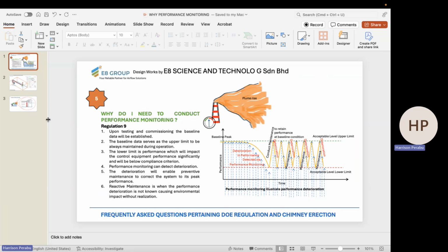Now, this notification process is actually also an engineering design permitting process, whereby, first of all, upon the identification of the airborne hazard, the right type of geometrical shape of enclosure or the right type of geometrical shape of an exterior hood is chosen. Right after that, the proper capture velocity is introduced, which would convey air outside towards the hood so that the airborne pollutant can be removed at the point of generation.